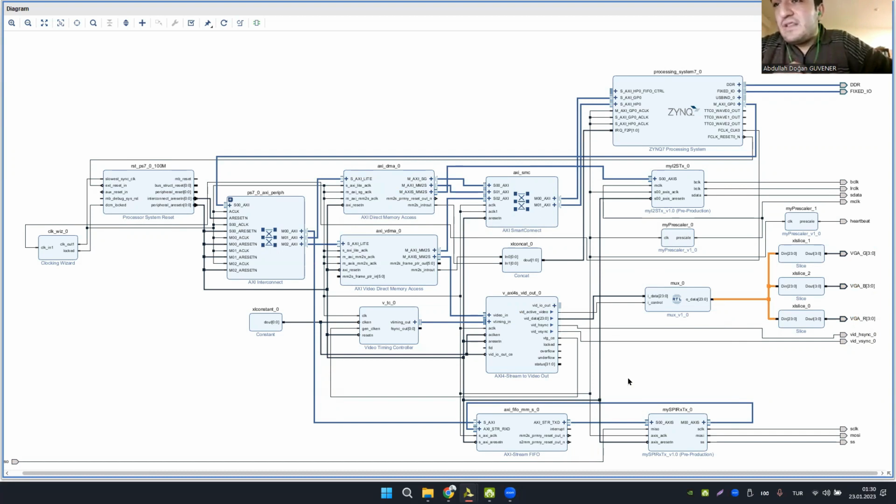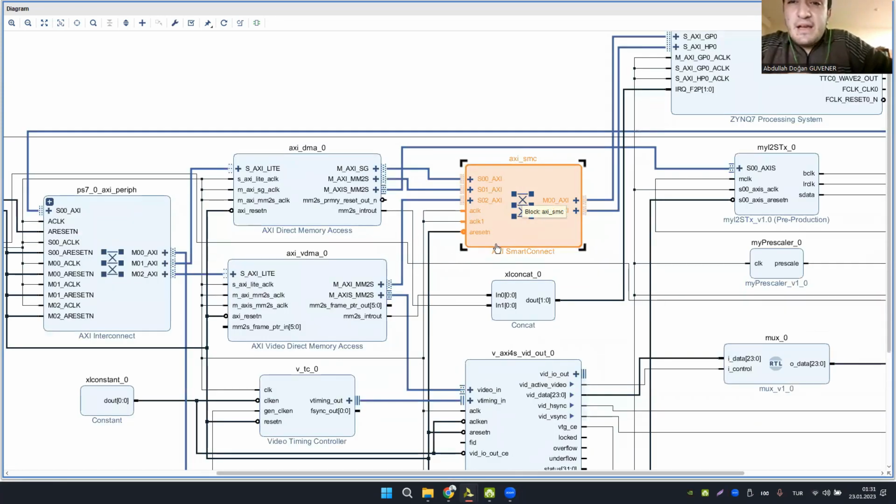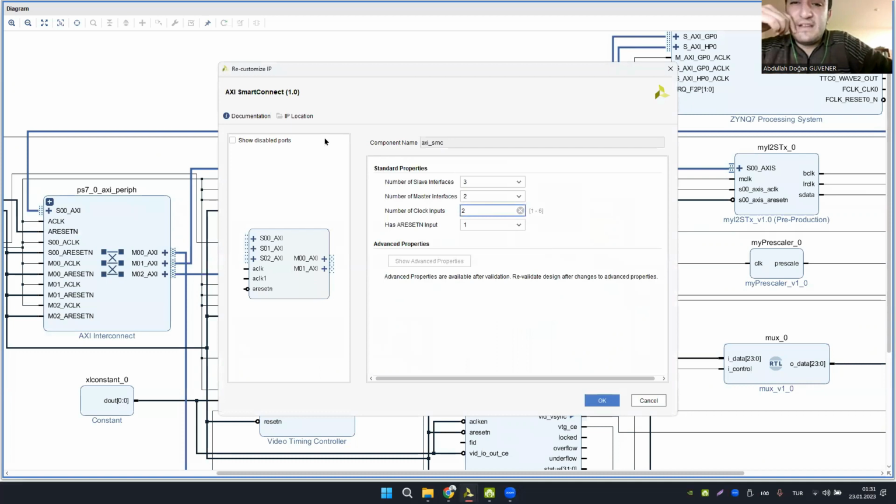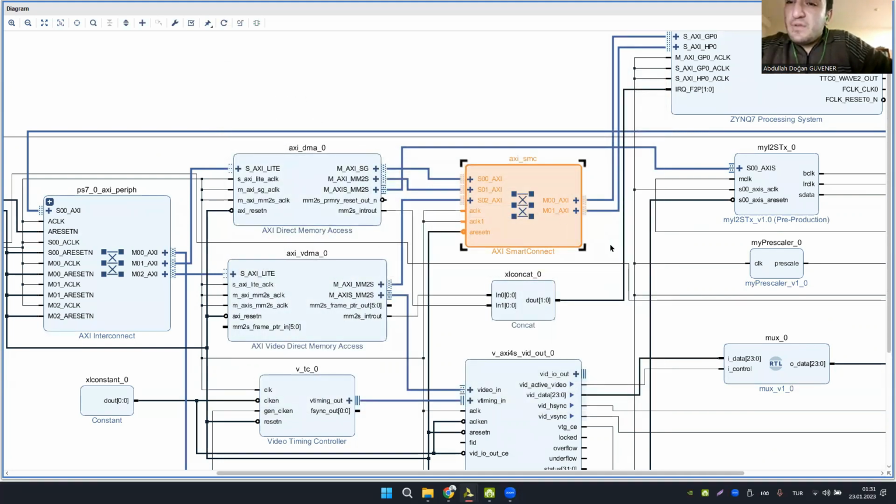Another important thing is coming from the auto generation part in Vivado, the AXI Smart Connect. At the left upper corner, we can see it. It is the feature in Vivado that allows for easy connection between the AXI, Advanced eXtensible Interface buses, and it automatically connects the AXI interfaces and generates the necessary interconnect logic, saving time and reducing potential errors while designing the whole process.